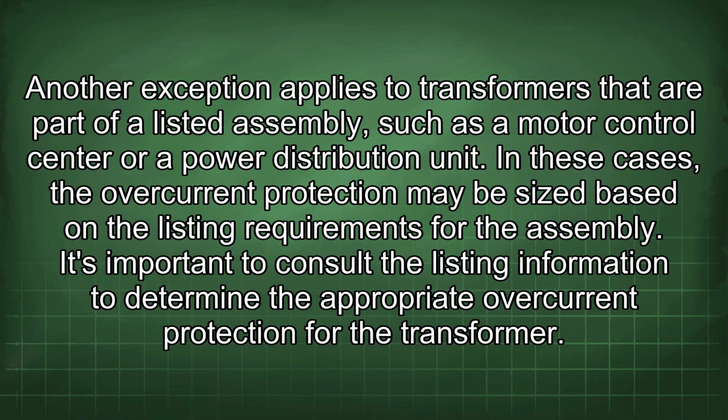This allows for a higher overcurrent protection rating, as the internal thermal protection will trip the circuit if the transformer overheats. Another exception applies to transformers that are part of a listed assembly, such as a motor control center or a power distribution unit. In these cases, the overcurrent protection may be sized based on the listing requirements for the assembly. It's important to consult the listing information to determine the appropriate overcurrent protection for the transformer.